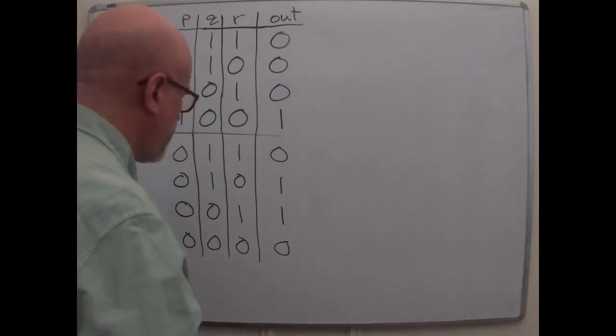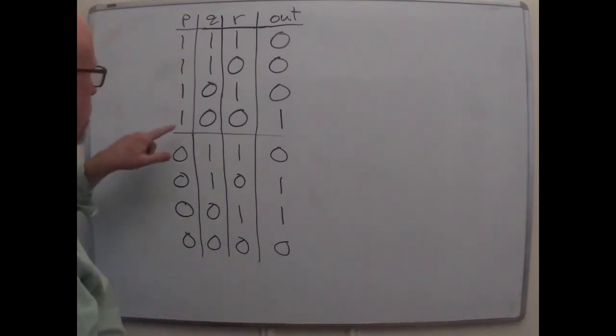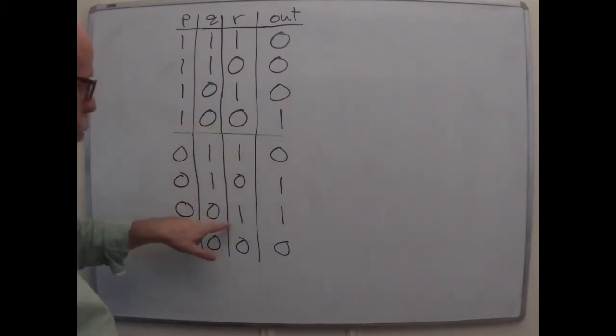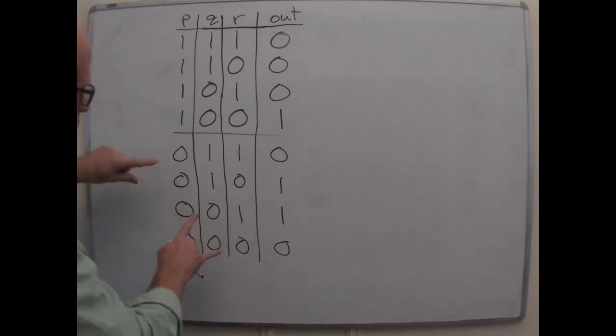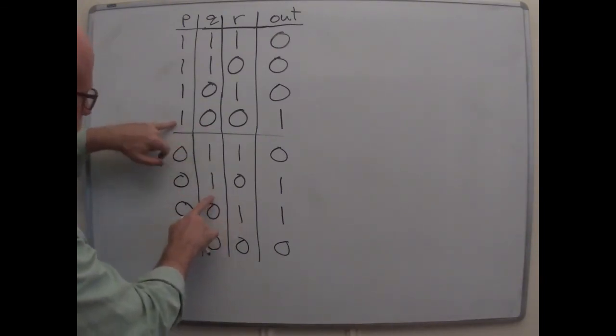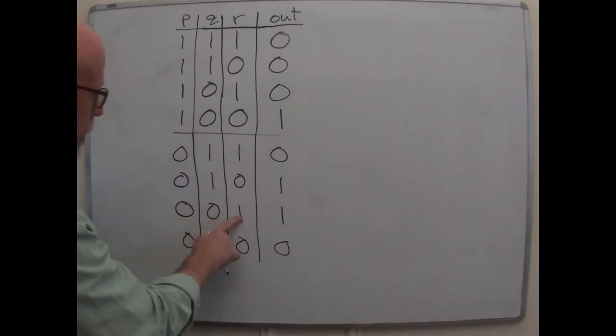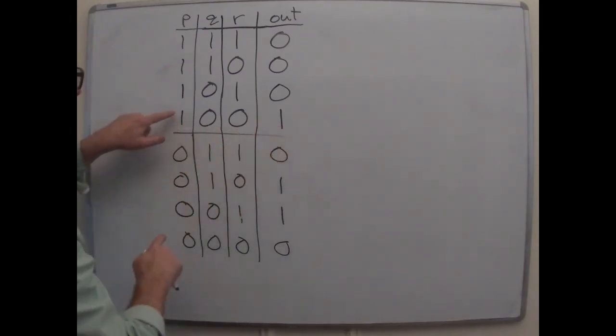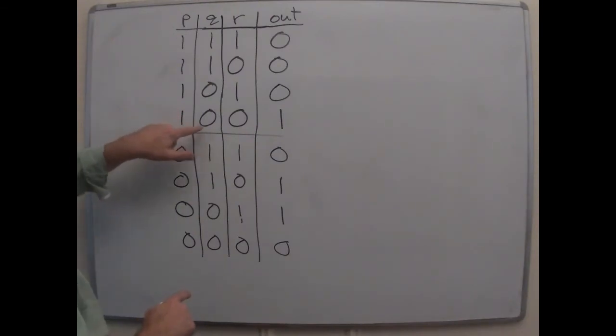So we are going to need to recognize 1, 0, 0. We'll also need to recognize 0, 1, 0, and 0, 0, 1. Oh look, that's by random chance, I think I just picked the ones that have a single 1 in them. So, looking at this first one, it's going to be P, ANDed with the negation of Q and the negation of R.